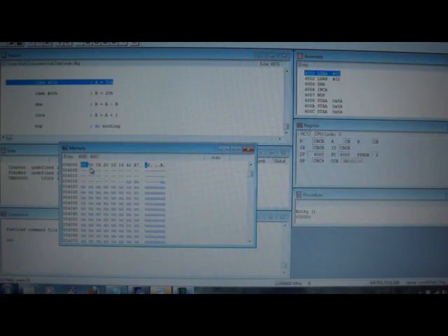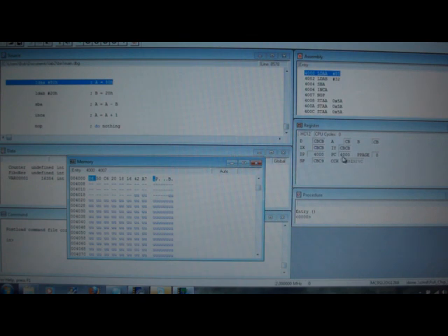For instance, 8650. That machine code stands for LDAA #50 hex. And we notice that that is located at location 4000, which is the first statement in our program. And notice that the program counter is sitting at 4000 conveniently for us to execute.